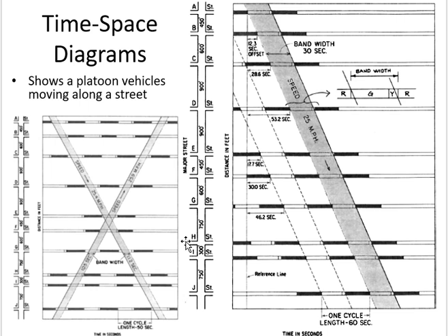So what we do is you plot the entire thing. Green, yellow, then red, then green, then yellow, and all that for 2-3 cycles on all intersections. Then you try to plot these two lines within the green. The two lines are my bandwidth.